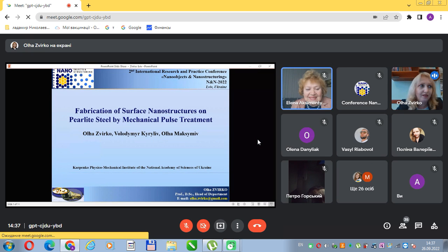Yes, and today I'd like to talk about fabrication of surface nanocrystalline structures on structural steels using the mechanical pulse treatment method developed in our department, and also how they influence mechanical properties and their interaction with hydrogen.